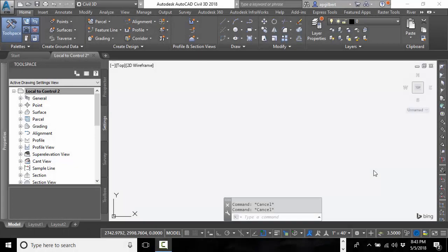Hello everyone. Similar to last week, in today's video, we're going to be rectifying a survey data file into known control in the survey database. The difference from last week is that in that video, our original raw survey file was in conventional format, that local coordinate file that we brought into the control. This week, we're going to bring in a local control file that is static format, so fixed coordinates. So I can't bring it into the control and have all the points fall out because they're not tied together by distance and angle. So let's get started.